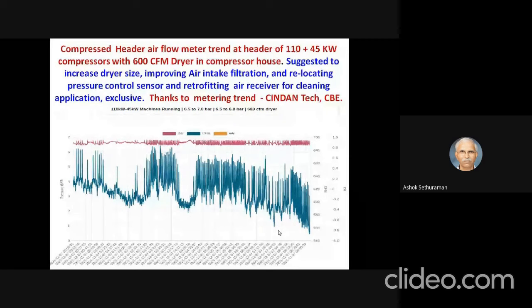This is where many of the industries are turning a blind eye. In fact, the IoT people can come in and have air intake delta P monitoring and control also, as regular monitoring. See, the air intake paper type filters can reach almost 3000 pascals every 3 months. You don't allow the filter to choke to 3000 pascals. Wherever the filter is crossing 500 pascals or 1000 pascals, you start cleaning the filters or pre-filters. Automatically, the compressor will be in a healthy mode to deliver the output.